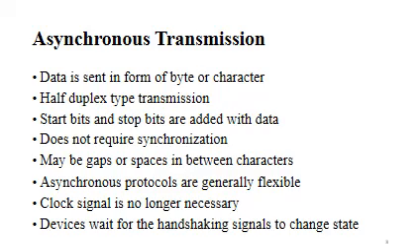Asynchronous protocols are generally flexible, since all the devices that need to exchange information can do so at their own natural rate, be it fast or slow. A clock signal is no longer necessary. Instead, the devices behave asynchronously, waiting for the handshaking signal to change state, indicating that some transaction is about to commence.